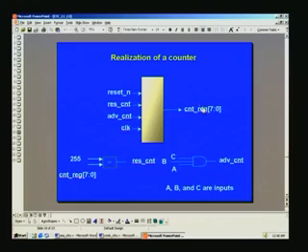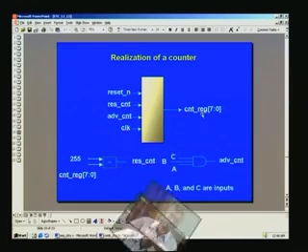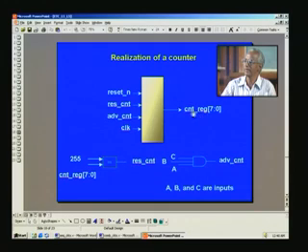Right. In the counter, we have declared it as counter reg, only to facilitate its being a register. All flip flops are basically registers, right, and it is 8-bit with the MSB once again here. If you want to advance the counter, you base it on the ABC status. If all of them are 1, then only do you advance. That is what is applied here.